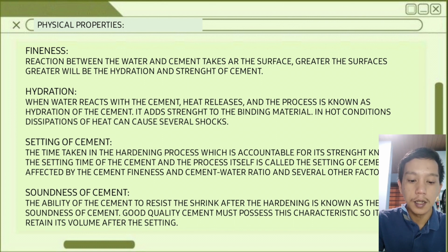So the next one is the hydration. Hydration, when water reacts with the cement, heat is released, and the process is known as hydration of the cement. It adds strength to the binding material. In hot conditions, dissipation of heat can cause several shocks.